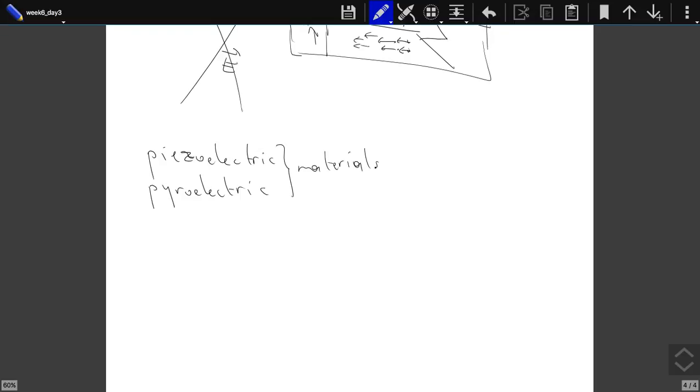There's a more common one. If anyone of you is smoking, you are constantly using one, probably. Lighters. You see when you click some of them, there is just this spark. So that is created by a piezoelectric material. If you compress a piezoelectric material, it creates a large electric field. So what happens in the lighters is that you are basically compressing a spring, and once the spring is compressed beyond the critical limit, a mass is released with the spring, and it hits this piezoelectric material, compressing it.